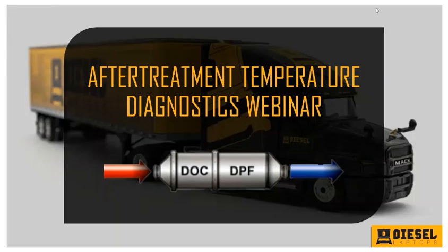One of the things that I tell technicians all the time is, when I force a regeneration with my service tool, if I hook my computer up and force a stationary regeneration, I'm doing that for one reason. I'm doing that for diagnostics. I'm not doing that to just regenerate the truck. Now, after the regeneration is complete, if that's all it needed, perfect. But generally, if a truck comes to you for regenning consistently or regenning too often, running a forced regeneration on it is not going to fix it. There's something else going on we need to address.